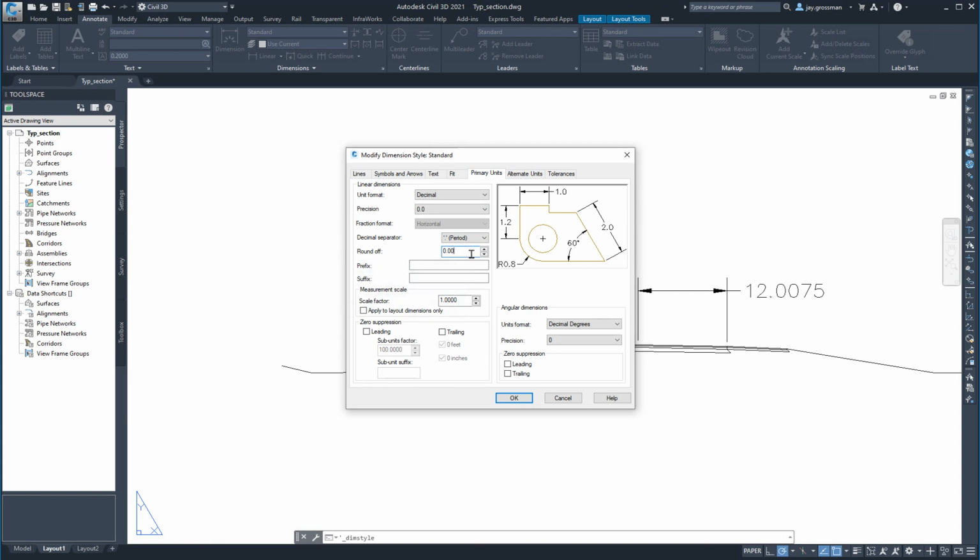Well, that's just how it's going to be. This is the one we really need to fix. We want it to be 0.0. I like decimal. I don't like inches. Typically for engineering, we don't use feet and inches unless you're a bridge designer. Then you like 16ths for some unknown reason. But highway people keep everything in decimal feet, going to the nearest 0.1, unless you're doing stations or elevations, and we go to the hundredths place, 0.00 for that. And that all looks good.